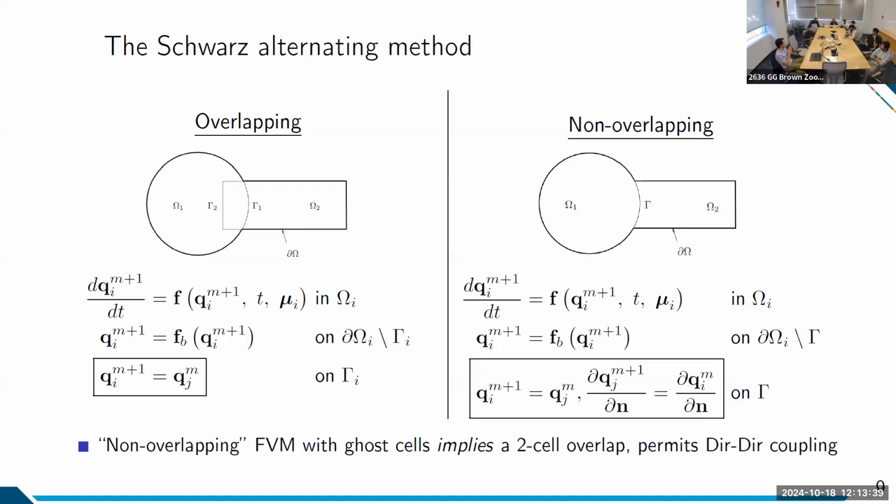I see. I am much more familiar with non-conforming meshes where we have hanging nodes. Is it something similar, where we apply constraints to make sure that they give us physically reasonable results? I mean, you'll have to have some guarantees of your mesh quality in the interior, but you can have arbitrarily non-uniform meshes in each of them, and then you'll have some sort of projection operator to project the solution from omega 2 onto gamma 1. In the simplest terms, a linear interpolation would be a projection operator, but you can certainly get more accurate.